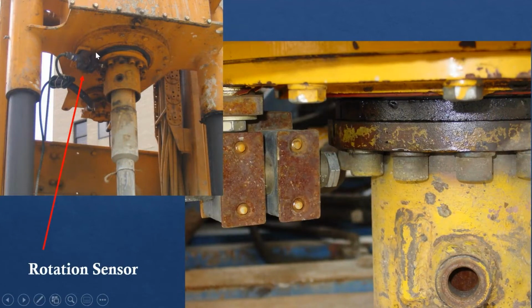This is the rotation sensor. It's an electromagnetic sensor, and on most of the rigs, especially the hydraulic rigs, you have the drill head in here, and it has a series of bolts, usually 10 to 12 bolts. What we do is we set up this sensor maybe about a quarter of an inch or so from the bolt. It knows whenever a bolt goes by, it counts. And so you can put it in the computer system that you have 12 bolts in there. Every time you see 12 bolts, that's one rotation. That way it can measure the rotation rate.